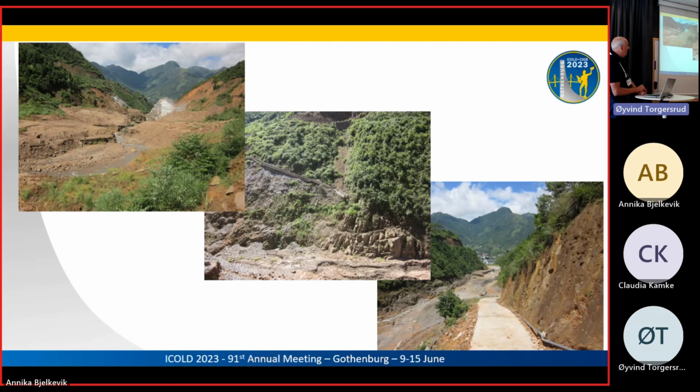This is also a good example of why you couldn't build an emergency spillway, because at the time of that event, the power went out, the telephones went out, the roads were washed away, so the site had absolutely no way to warn this village downstream, which you can just see in the bottom right corner. About an hour after the water overtopped the dam, it failed and killed, I think, 4 or 5 people in the village down below. So it's a good example of not having a spillway, or not having a safe spillway, and also the things you really have to think about in an emergency response plan.